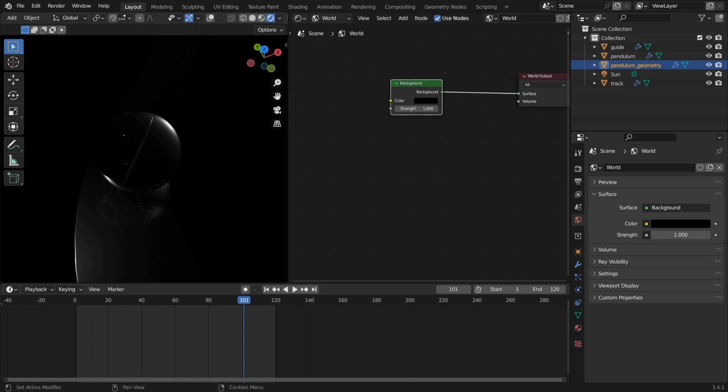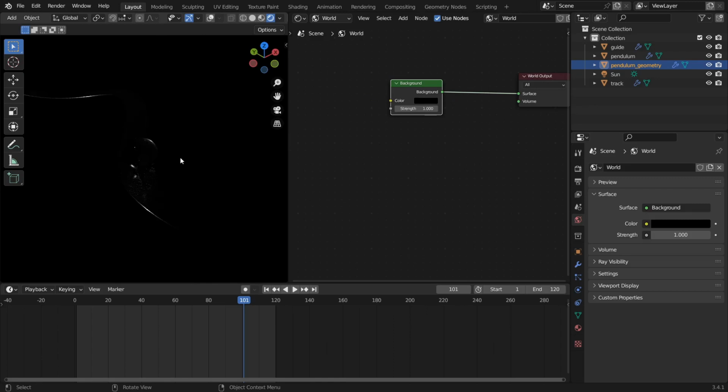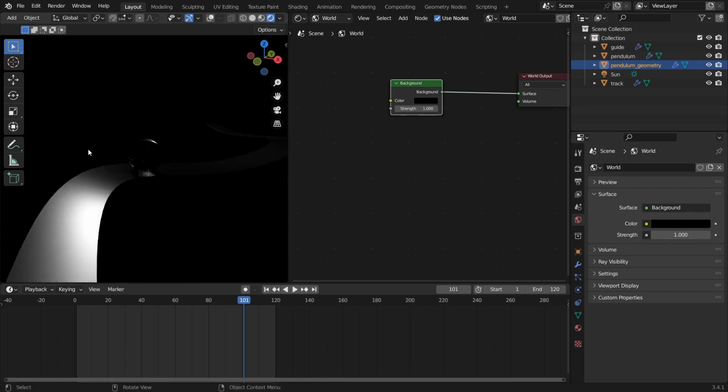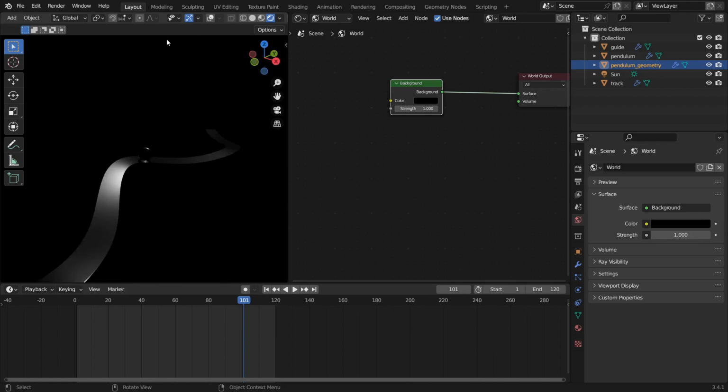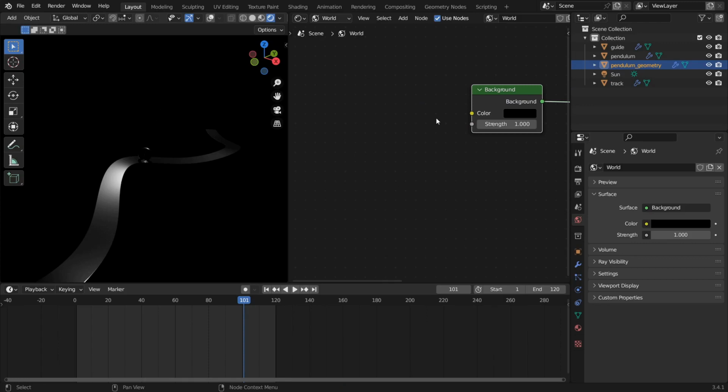So what I'm going to do here is I'm actually going to add in lighting that has a gradation from black to white, where the top of the world sphere is just white and then it sort of fades out to black at a certain interval. This is a really useful lighting setup for a lot of different scenarios, and it's super, super simple.